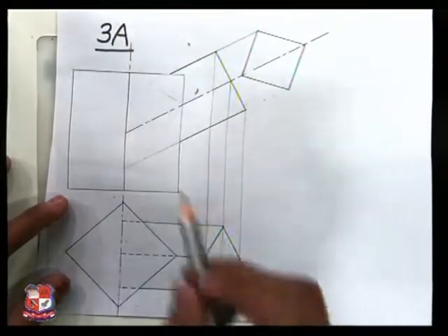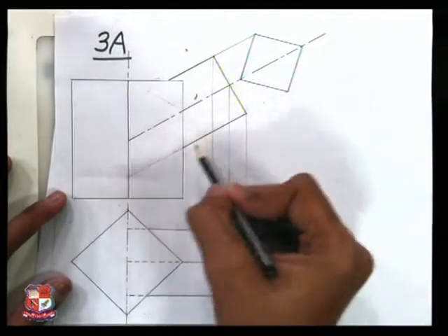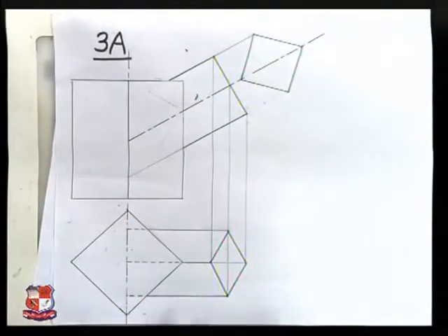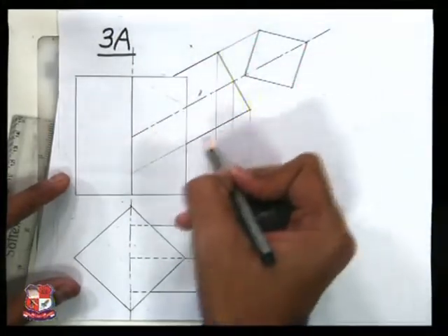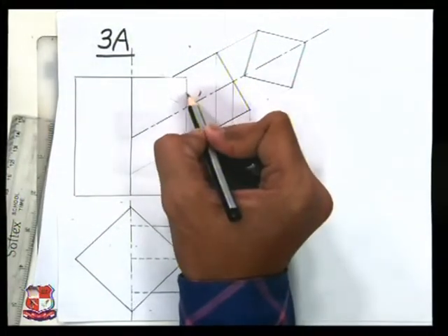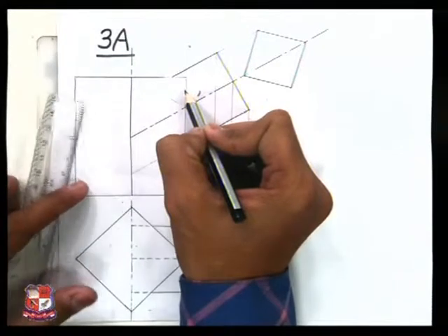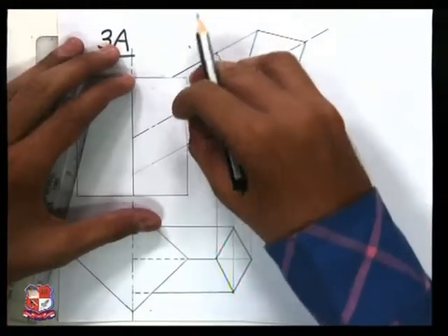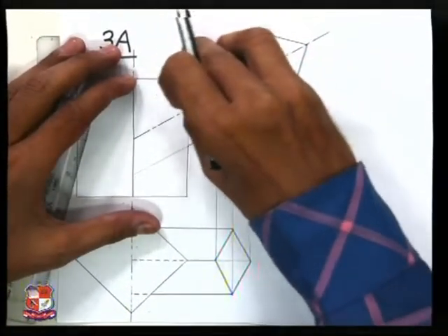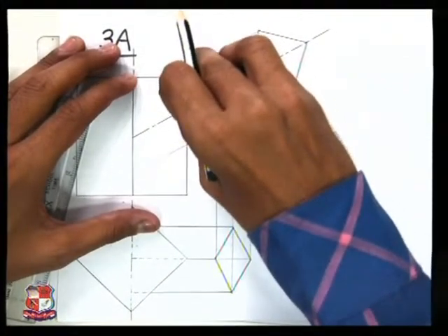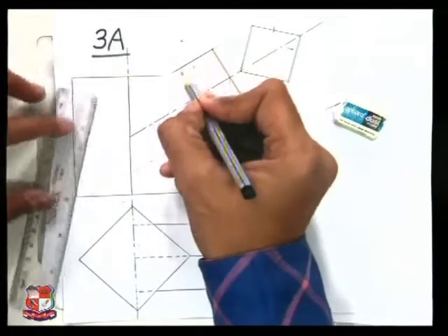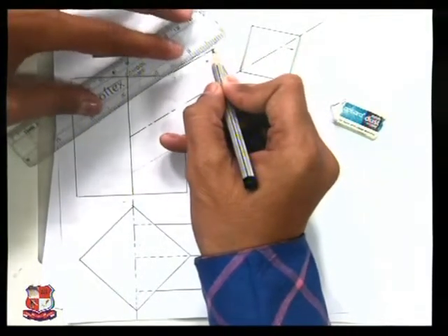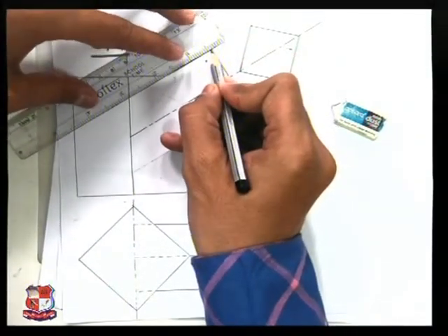Now what's about this front view and these lines? Which type of line would appear? You can see here, once the branch passes through, this edge would be trimmed off. It will not appear. So we have to erase this corner because it's a removed portion for this solid. It will not appear, and hence this branch would appear from here to here.